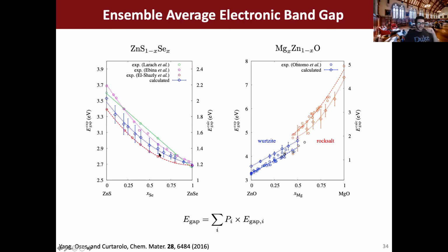As I change the concentration of the selenium, the system is going to decrease the band gap, and the relationship of how it decreases is quadratic. You see that it kind of looks like x squared. It's not really linear, although there are some people that say it's linear. There's some debate there, but the consensus is that there's this curvature to how it decreases.